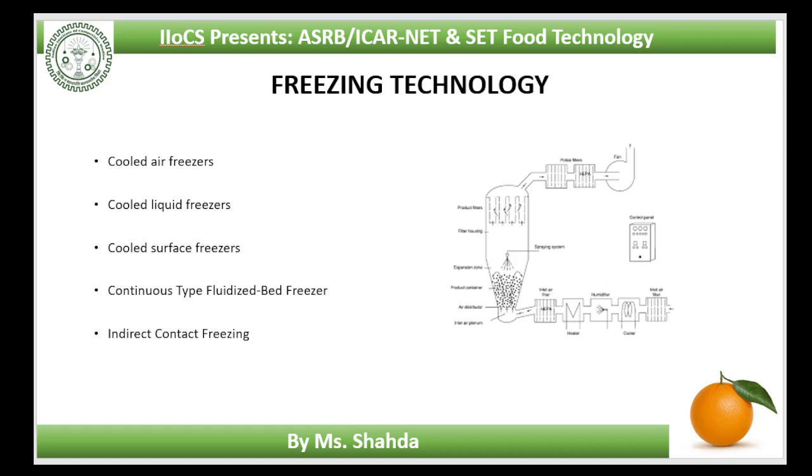An interesting feature of this unit is continuous and automatic defrosting. Air is blown via a fan through cooling coils and up to the porous food trough. Cold air tends to condense its moisture onto cooling coils. A spray of propylene glycol antifreeze is maintained over the cooling coils to melt ice as it forms. In this way, cooling coils are maintained at maximum operating efficiency.